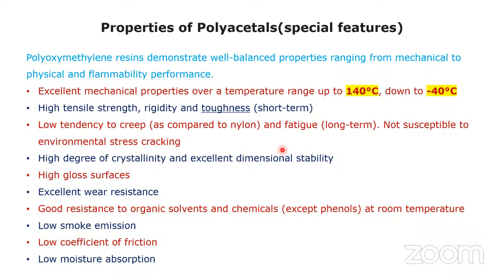Okay, it is having high tensile strength, rigidity, and toughness. Okay, then low tendency to creep as compared to the nylon. Okay, and fatigue, not susceptible to environmental stress cracking. Then a high degree of crystallinity and excellent dimensional stability, as we have seen in the structure of polyacetals. The structure itself shows the high crystallinity. Okay. Then high gloss to the surface.